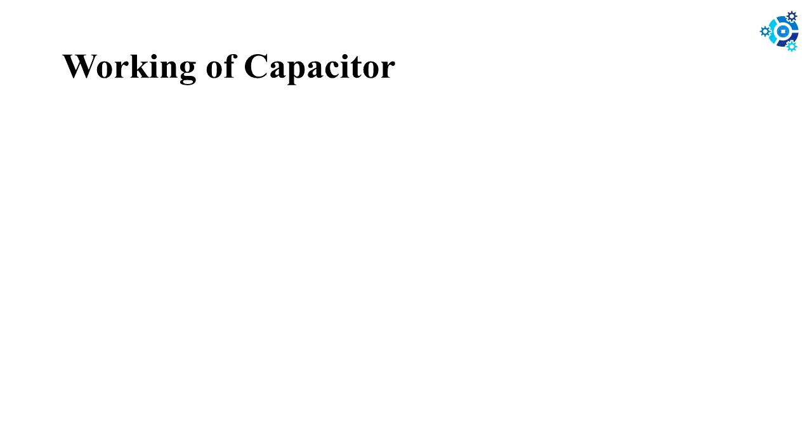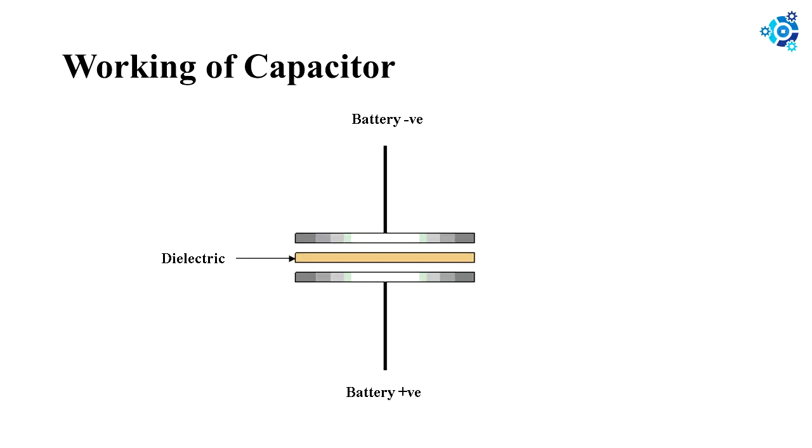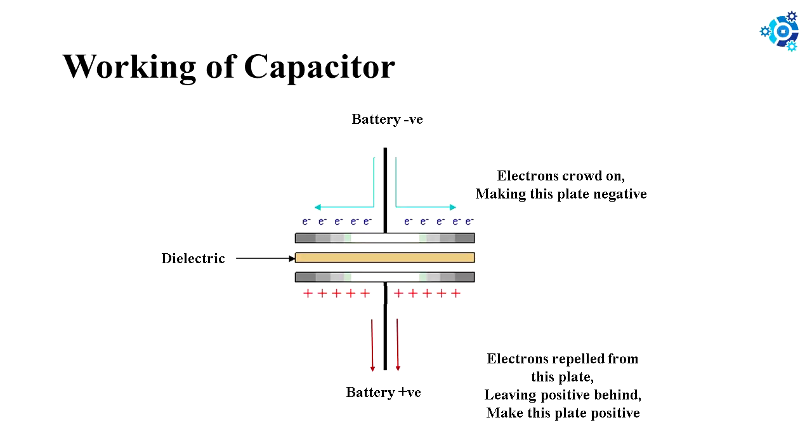How a capacitor works. We know that electric current is the flow of electric charge. When current flows into a capacitor, the charges get stuck on the plates because they can't pass through the insulating dielectric. Electrons, negatively charged particles, are sucked into one of the plates, and it becomes overall negatively charged. The large mass of negative charges on one plate pushes away like charges on the other plate, making it positively charged. The positive and negative charges on each of these plates attract each other, because that's what opposite charges do.